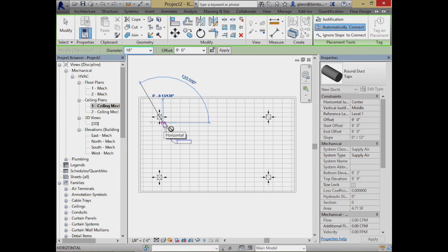To the extent that you can have things come off at nice smooth bends as opposed to 90-degree bends, you tend to be better off. So what I will do is get ever so close. I won't actually connect to it yet, because when I finally do connect to it, I like to use a flex connection, which gives a little bit of flexibility. You don't want too much flex duct, it's less efficient, but it gives you a little more variability in where that thing actually ends up. Putting hard ducting in is actually pretty hard to do.